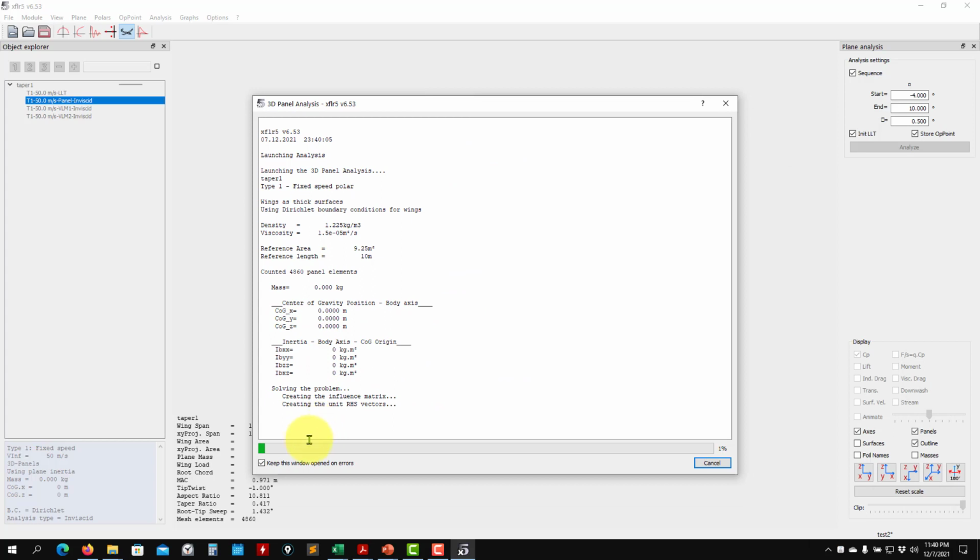You're going to see that it is much slower. See, that's telling you, and this is where you are putting all the computational effort. Constructing that is not that difficult. All your computational effort is going there, in inverting that matrix. So it wasn't that big, and actually 30 by 30, there are not many panels, and it's taking a long time. So let's wait a little bit. See that this is the number of panels that we have. So that is not that much, but it's taking a long time. It needs to compute all that matrix of influence, everything.